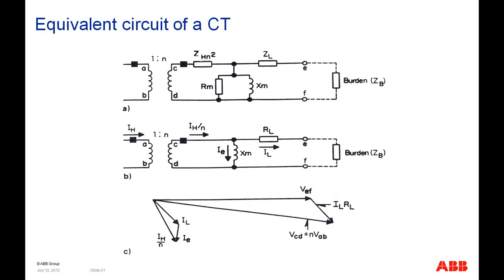By definition, the C designation for current transformers says that the amount of magnetizing current that we draw, this IE that you see in the picture, can't be greater than 10% of the rated current going through the current transformer up to 20 times rated current. So that means that if I have a 5 amp current transformer and I put in 20 times rated current, that would be 100 amp secondary. And for 100 amp secondary, I can't have more than 10 amps flowing through IE. And we'll show that a little bit more, a little later when we get into some calculations.